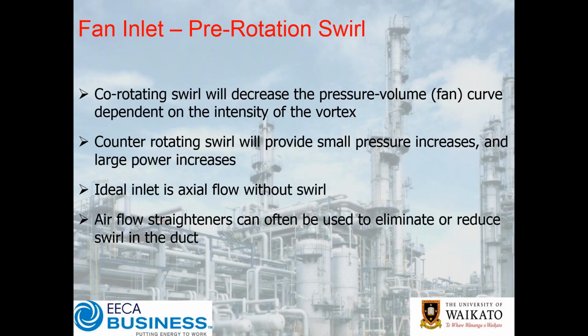Like I said, the fan I mentioned previously that had a high vibration at the inlet, they were treating it as an open inlet, but the cavity that was feeding the fan was actually quite tight, so it ended up behaving like a ducted inlet, and there were some really nasty vortices induced in just the wrong spot in the duct. So you have to be very, very careful.